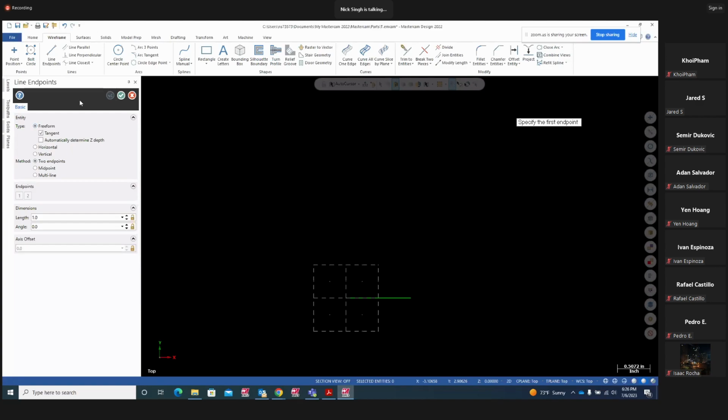So create a line. We are still in the same line option, same command, and that's my line right there. So this angle is going to be 180 degrees minus 45. So you can put here angle 180 minus 45 degrees, 135 degrees.